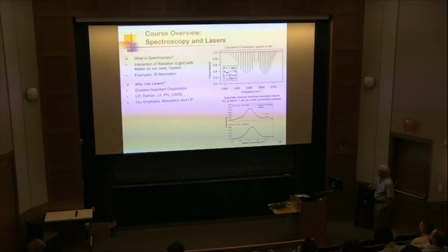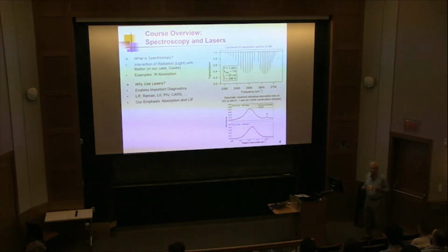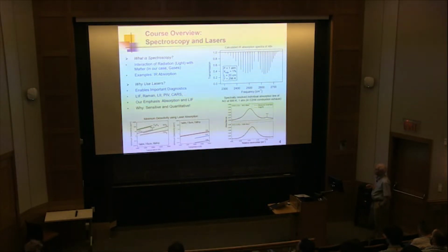LIF stands for laser-induced fluorescence, Raman spectroscopy, laser-induced incandescence, particle imaging velocimetry, CARS, that's coherent anti-Stokes Raman spectroscopy. I'm going to focus mostly on absorption and fluorescence because they're techniques that can be made quite quantitative and beneficial. Now let me show you how sensitive they can be.